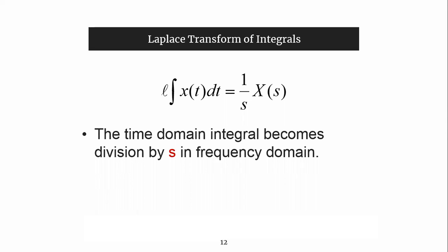Similarly, if you want to convert into the frequency domain, how is it possible? That is the Laplace of the integral of x(t) dt, which is equal to 1 by s times X(s). See here, this is in the form of the time domain, and this is in the form of the frequency domain.